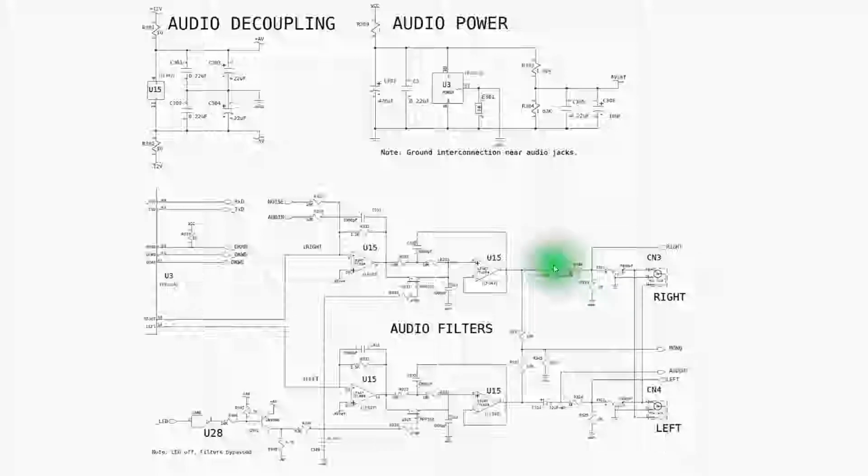Most likely my issue is one of these two electrolytic caps has failed. Don't know that for sure. If the cap has leaked, it's possible that the electrolyte has leaked out and etched away one or both of the traces, and so one of these traces could be open. So if I saw signal here and didn't see signal here, it could be an open trace, it could be a bad cap. The first thing I almost like to do is just replace these two caps.